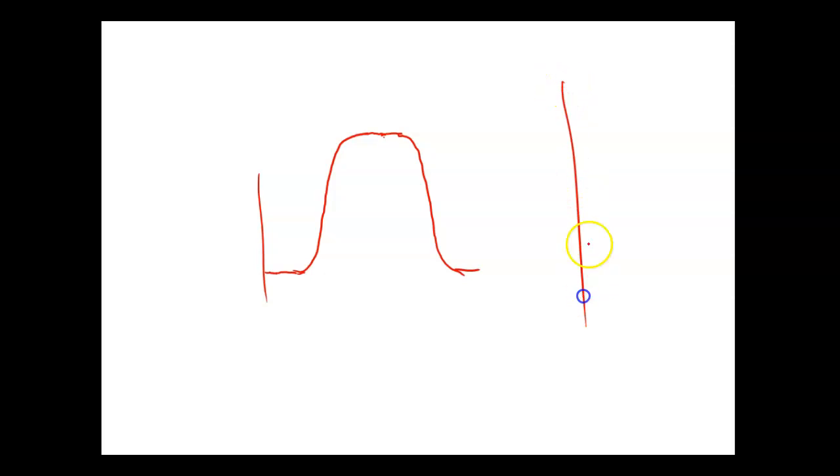So every media has a bandwidth. A conductor works really good at DC, and this axis is hertz, so this is frequency. But sooner or later a conductor is going to roll off, especially if you have two conductors running together. This is why high frequency is so hard. The military aircraft used frequencies so high that no other country could figure out how they did it, because ultra high frequencies are really hard to keep from jumping all over everything. Every two conductors side by side is a capacitor.